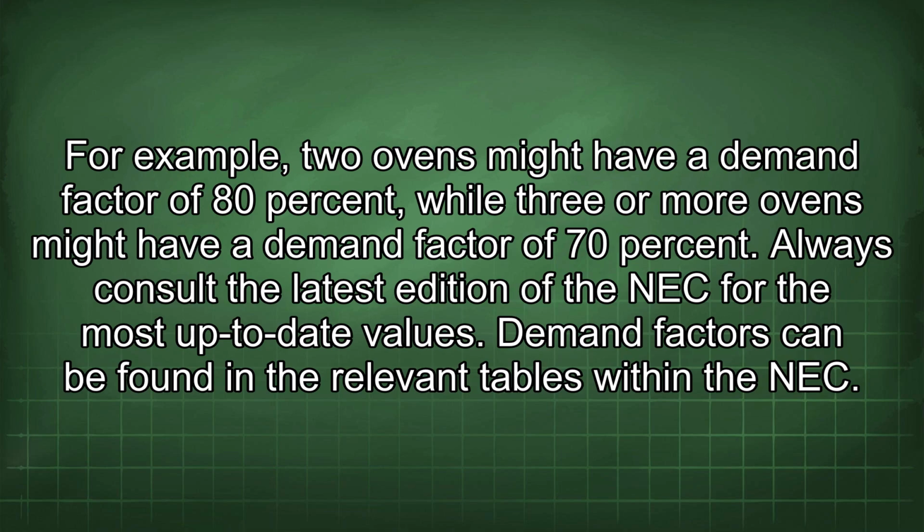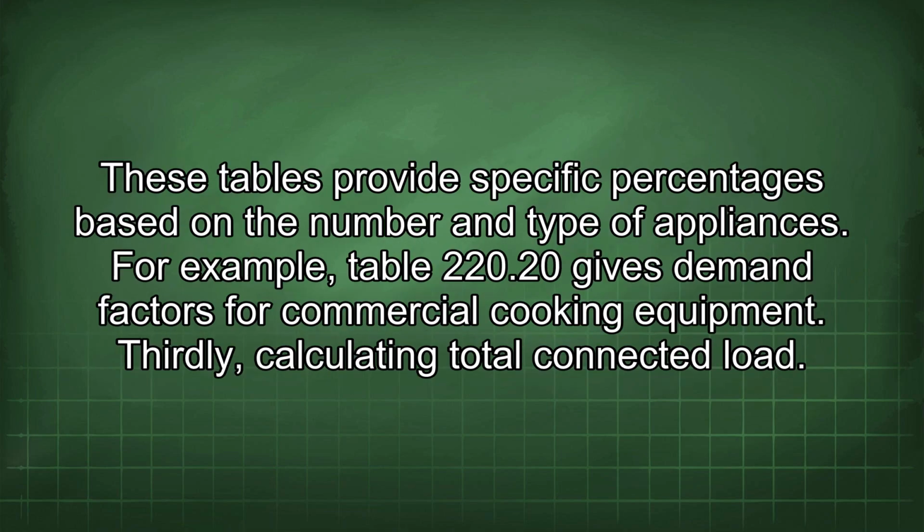Demand factors can be found in the relevant tables within the NEC. These tables provide specific percentages based on the number and type of appliances. For example, Table 220.20 gives demand factors for commercial cooking equipment.